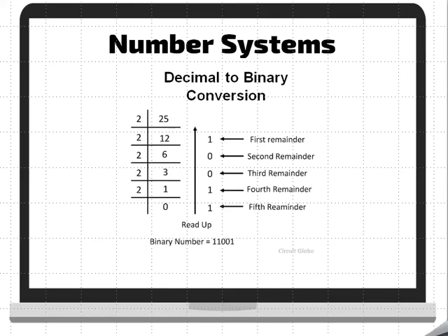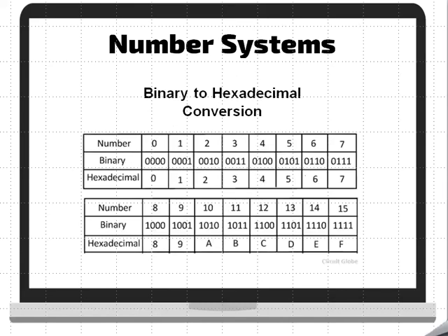So we also have different number systems, and for the conversion between these number systems, for decimal to binary conversion, we can divide the number repeatedly by 2 and simply take the remainder, as in the example. For binary to hexadecimal conversion, we group the binary digits into groups of 4 digits starting from the right, adding zeros at the left if there are not exactly 4 digits in the leftmost group, and convert each group of 4 bits into hexadecimal.